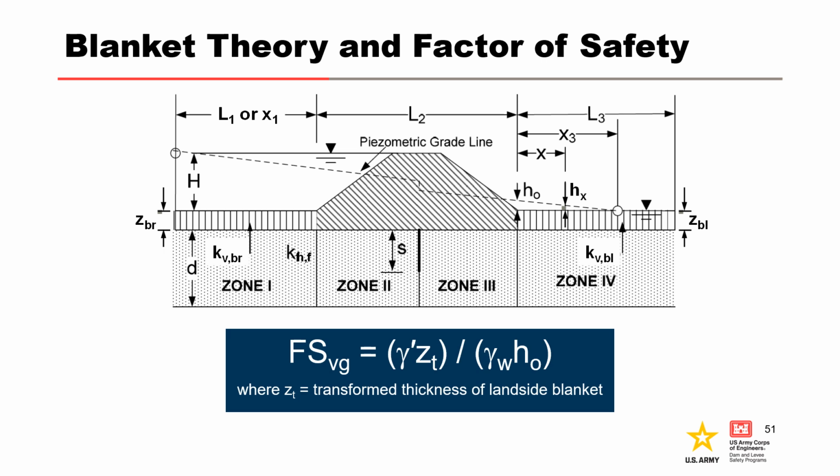The basic geometry of a levee under seepage analysis with a top stratum or blanket is shown. Unlike the results from SEEP/W analysis, which required the first-order second-moment method of reliability analysis to assess the probability of a factor of safety less than 1, blanket theory has a set of predictive equations for excess head, and hence exit gradient, that can be used directly in a probabilistic analysis to estimate the probability of a factor of safety less than 1 with the right foundation conditions and boundary conditions.